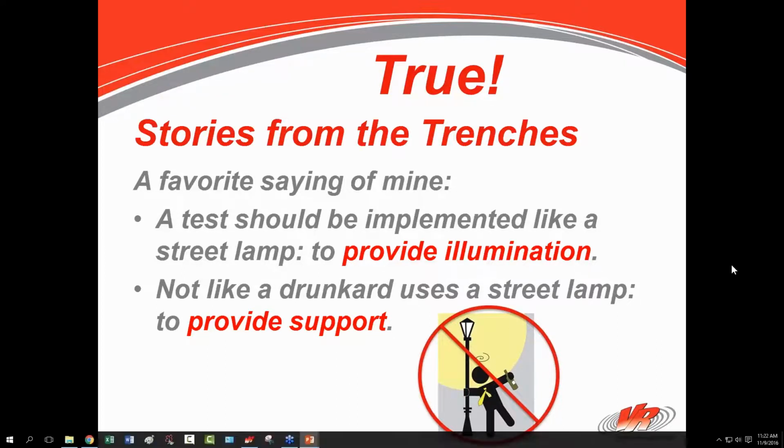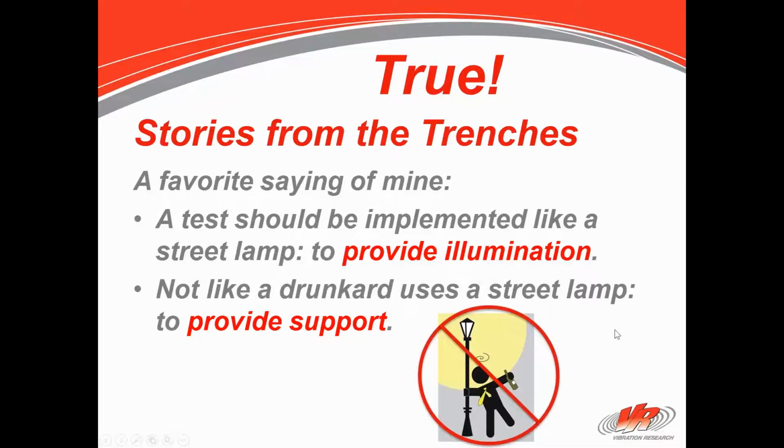And let me just make this statement. Why do products fail? Well, they fail because you found a resonance somewhere. That's true probably 99% of the time. It fails because something in your product breaks into resonance. Take a capacitor soldered onto a circuit board, a transformer mounted into your chassis. Everything that acts like a spring mass damper system, even the little teeny IC chips that are located on a circuit board, they may have resonant frequencies, typically up in the kilohertz, very high, but they can resonate. Circuit boards will resonate, usually at quite low frequencies. And when they resonate, that is when you have failures.